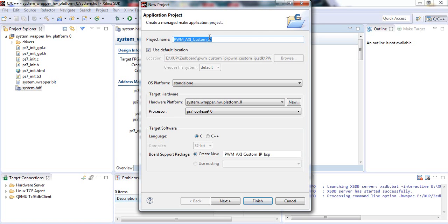The processing system consists of a dual-core ARM Cortex-A9 processor. ARM licenses these cores to Xilinx, so Xilinx includes these PS cores in the Zynq 7000 chip, which is also included in the Zedboard. We are going to implement our project on the Zedboard. The PL, programmable logic section, consists of the 7 series FPGA fabric, which is similar to other families like Artix-7 and Kintex-7, but they have more logic density than the Zynq family.